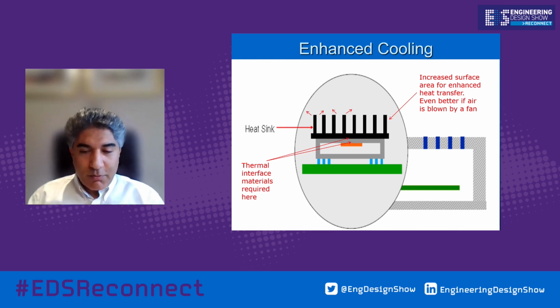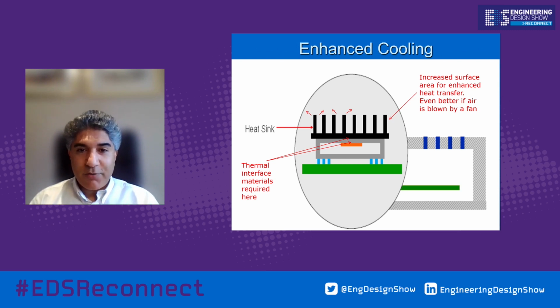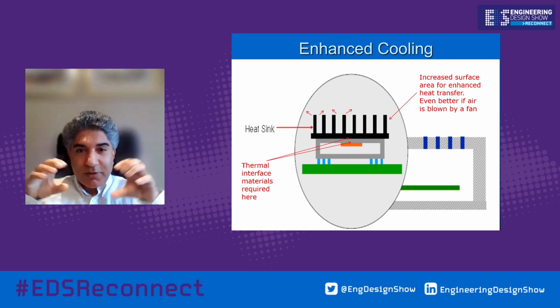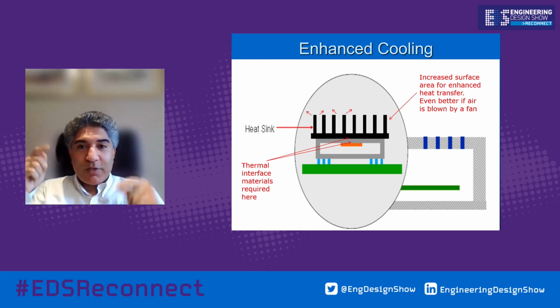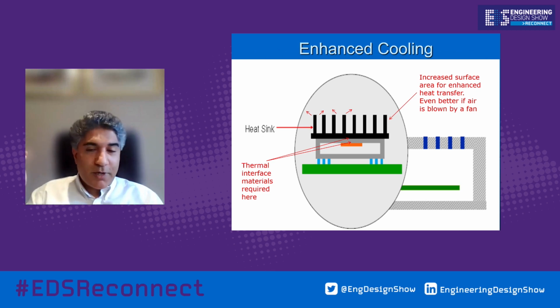Okay, so if you see a microprocessor, you have a heat sink assembled onto that. What we're trying to do is be better than air. You might have nooks and crannies in the heat sink, and that's where the thermal interface material is sandwiched between the heat sink and the component. You see the orange part, that's the die, where the component is, protected by a die and enclosed in its black housing. What we're trying to do is get the heat from the heat generating component to the fins and out, and if you have a fan, it could obviously provide enhancements in the heat dissipating properties.